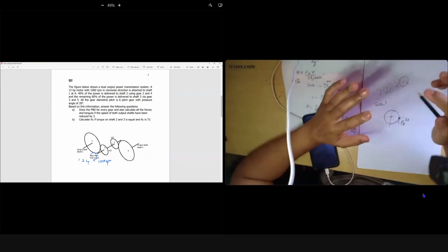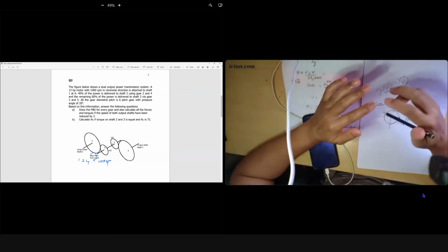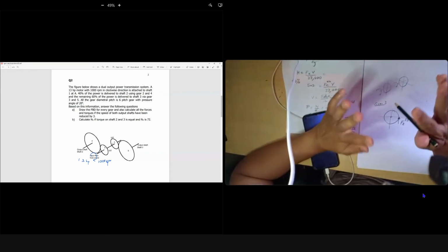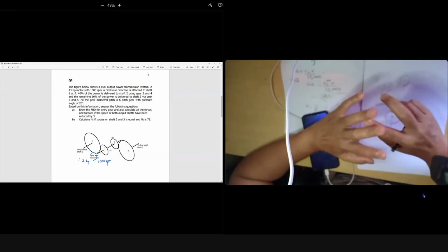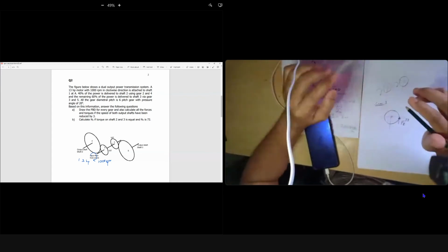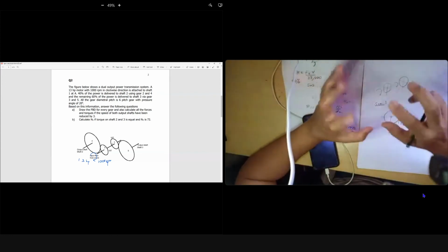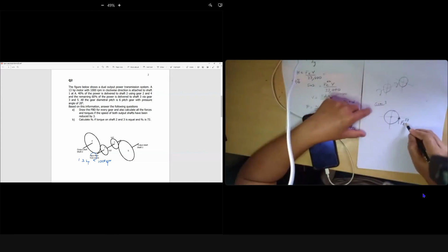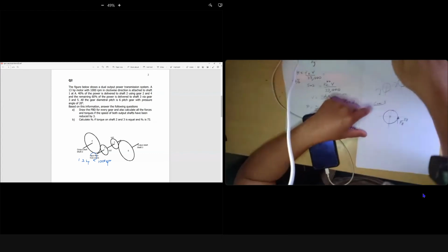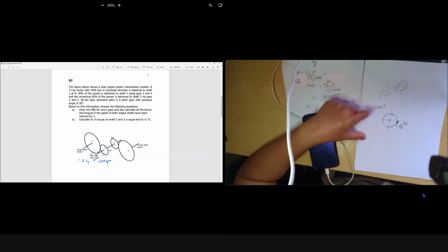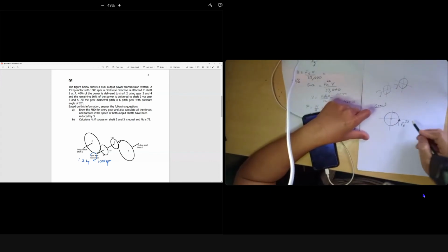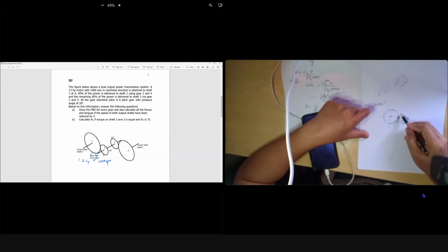But it is said that for this one you cannot say the summation of torque is 0. No, cannot. Because in the normal case, like the previous example that we discussed just now, it is the pure transfer of power. But this one they divide, do you see? This F tangent will not produce the same torque as gear 2. Do you understand for this case? Because it says it transfers 60% power here. Clear, class?